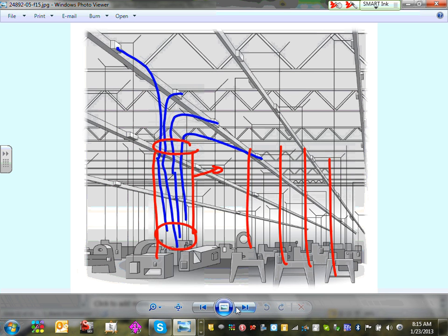Any comments, any questions, guys, about plug-in busways? This is your first and last time you're going to hear about plug-in busways. So, to summarize, we talked about 3 busways. We talked about the feeder busway, the blue thing, 2 of them on our manufacturing floor. Plug-in busways, these are the yellow ones, 225 amp each, and we have 1, 2, 3, 4, 5 times 2, 10 of them.